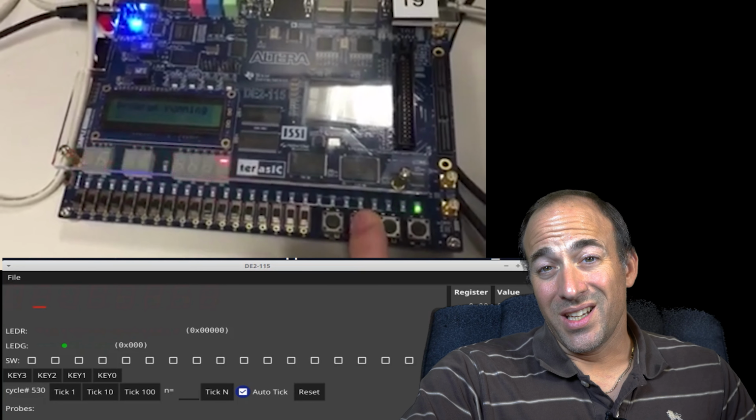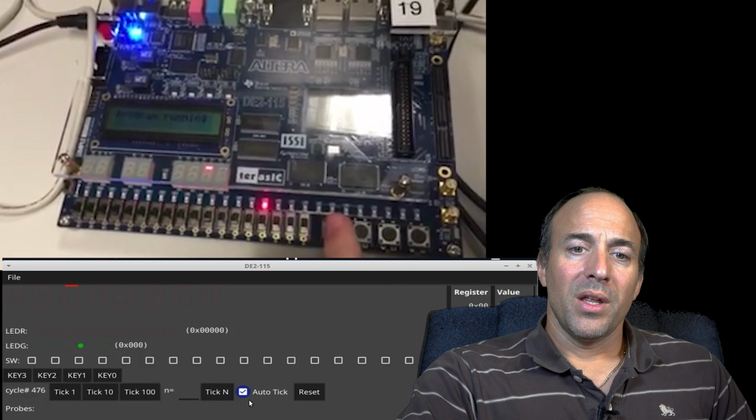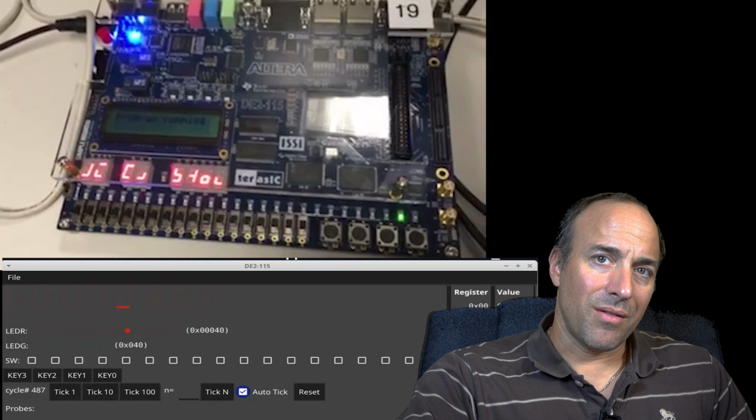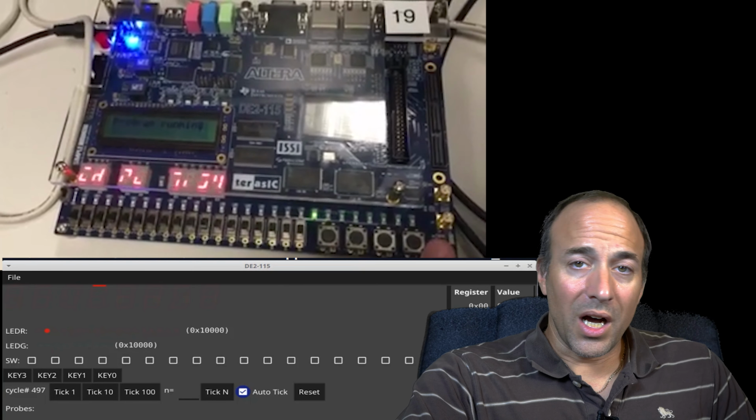So it combines your SystemVerilog with its own simulator and integrates them together into one blob as a C program that can be compiled and run as a software library. This makes it really easy to write other software that interacts with the simulated behavior of your SystemVerilog.